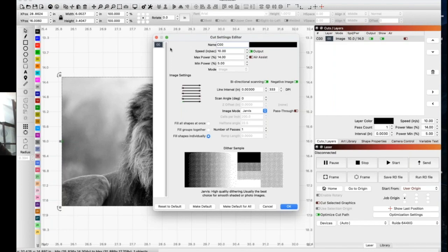Power is going to completely depend on material. Say we took a piece of acrylic and lightly painted it with some flat black, and we just really want to pull off that layer. I'm close to the firing threshold of the laser, somewhere around 9, 10, 11. I'm barely touching the surface, just picking away dots, and that's all that I'm doing. Otherwise you're blowing out all of those dots around the dot, wiping away material or paint. It's like using a Sharpie instead of a fine point pen.